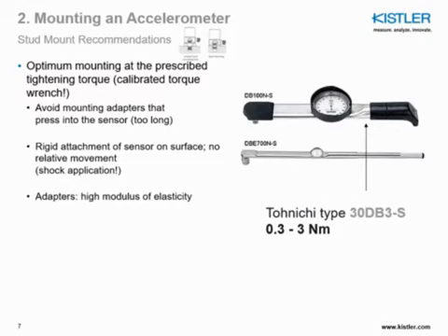On the other hand, if you over torque, you can damage the stud, and more importantly, you can damage your sensor itself. Sometimes, for example, ground isolation bases are removed and broken off because of over torquing.